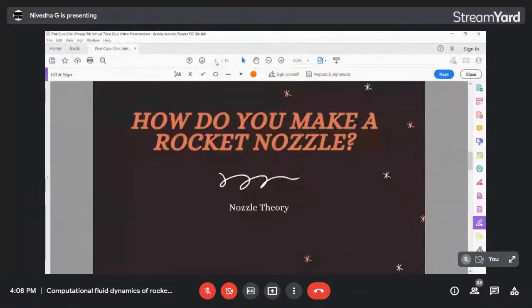We have this thing that is, so if you have a shock wave inside the nozzle, it is called an inefficient nozzle because your flow will not accelerate to the given Mach number at any cost. So your goal is to reduce shock waves in a nozzle. And how do you know where the shock wave is formed inside a nozzle? Using your CFD.